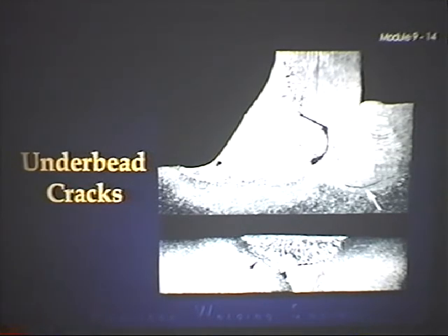It is believed to be caused by stresses within the metal that are the result of the unequal contraction of the base metal and the weld metal, the restraint of the cooler base metal, stresses caused by the expansion of the metal when martensite is formed, or stresses set up by the precipitation of hydrogen out of the metal to form molecular hydrogen.